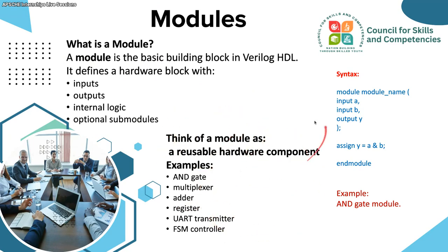Now we will come to the syntax part. Whenever you are going to define a hardware, you need the module keyword, and then the module name. The module name is something like an identifier.